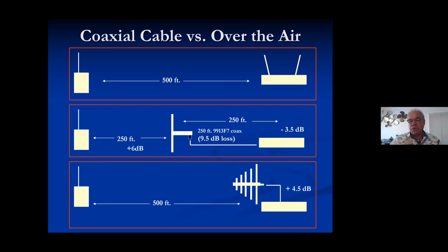So in that case, you would want to put your antennas as close to the artist as possible and increase your signal to noise ratio. The noise is the RF from the television. The signal is your wireless mic. In that case, running a long cable is completely acceptable. If you're in a very quiet environment in a studio where there's no RF interference, then you don't need the RF cable because it creates loss. Look at all the loss in this case. 250 feet, I would never run, but 10 dB of loss at certain frequencies.